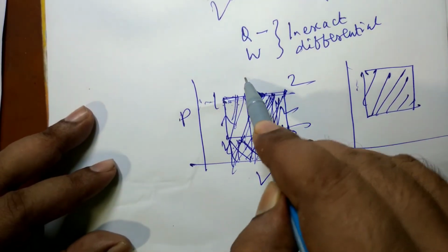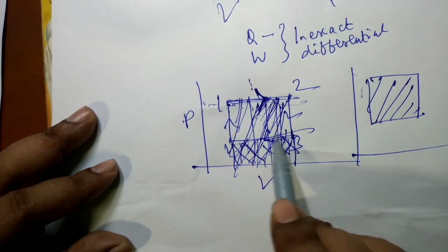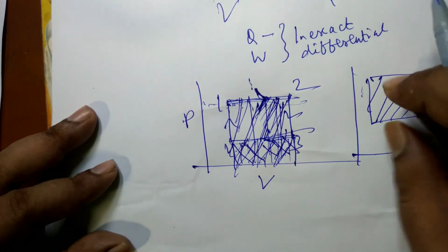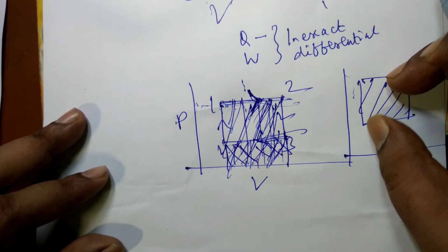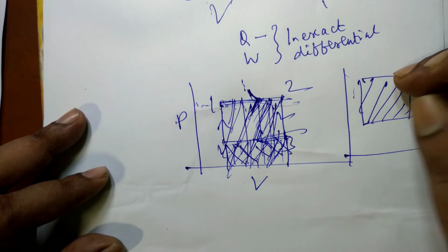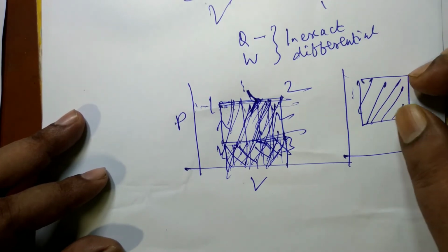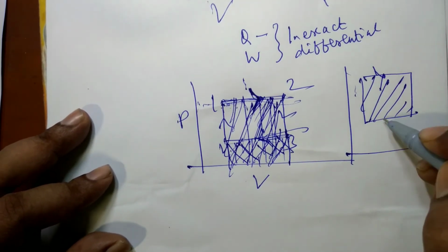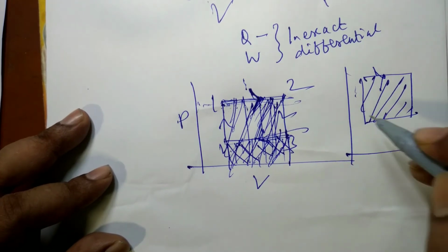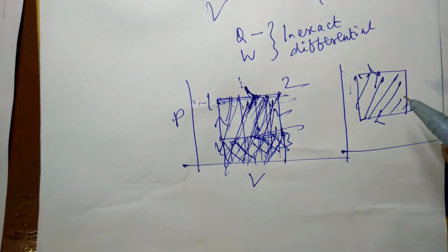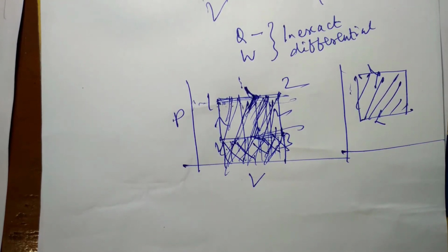यहाँ कुछ work produce हो रहा है और यहाँ consume हो रहा है, जो जितना नेट रह रहा है वो will be represented by the included area, this area of this cyclic diagram. So that's why if it is a clockwise, the net work will be positive, and if it is an anti-clockwise cycle, anti-clockwise means work consuming cycles on which the devices like refrigerator and heat pump operate, then there will be net work input, वहाँ work consume ज़्यादा होगा, जितना produce होगा उससे ज़्यादा consumption होगा वहाँ.